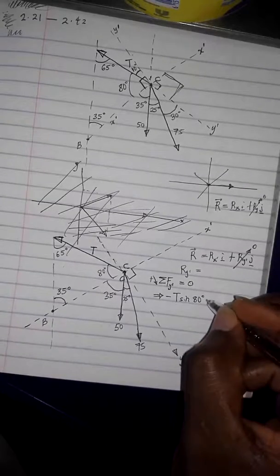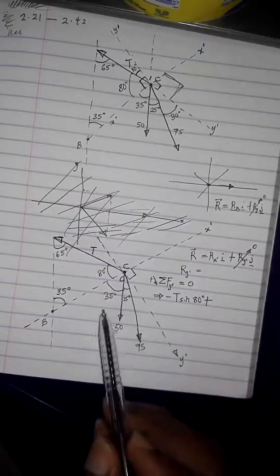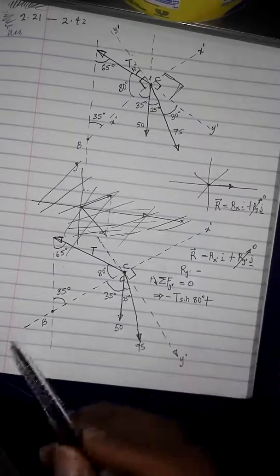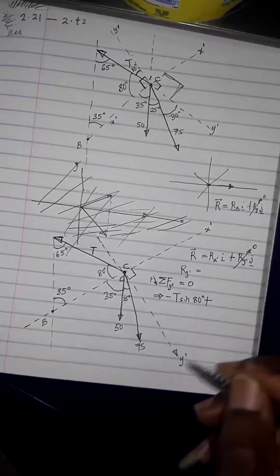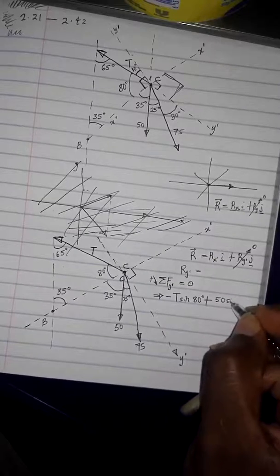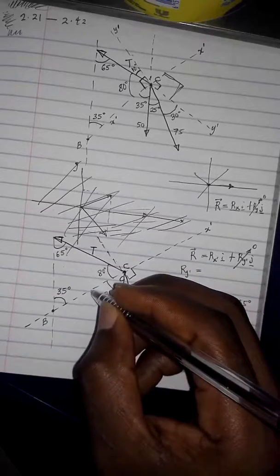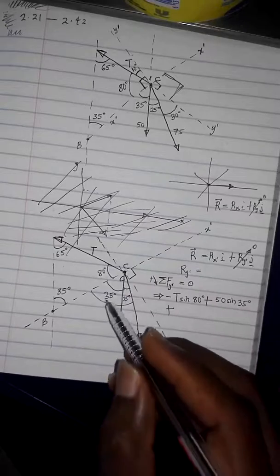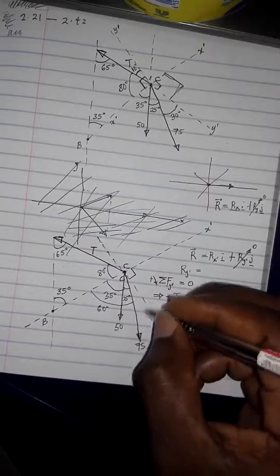Then I move on to the other forces. Plus, I have this 50 pound force making an angle of 35 degrees with my x prime axis. Its y component is going to be directed this way, and it's going to be positive, obviously, so that is going to carry sine also. So I'm going to have 50 sine 35 degrees. Then plus the next one. When you add these two angles, you know the angle this makes with the x-axis. That's 35 plus 25, so that's going to be 60 degrees. Or you say it makes 30 degrees with this, any one you want to use.